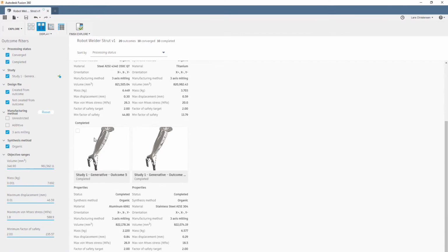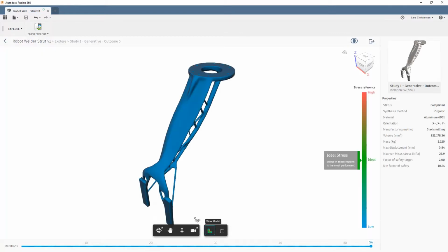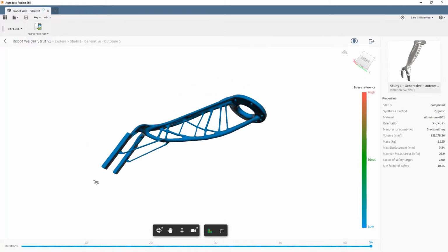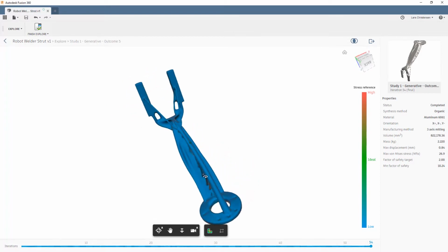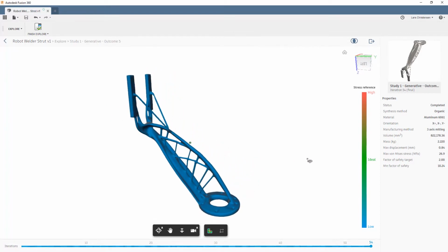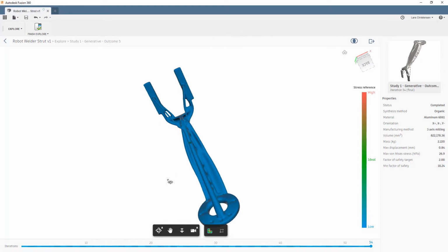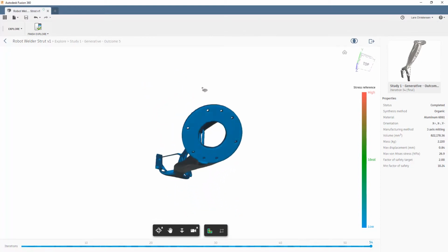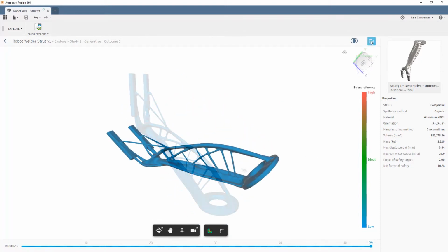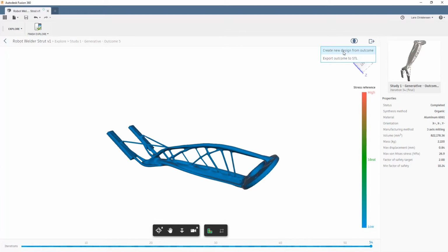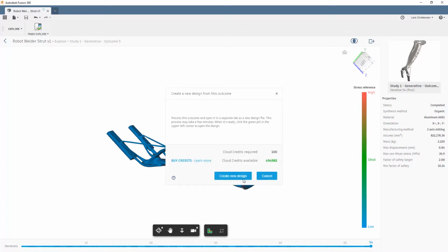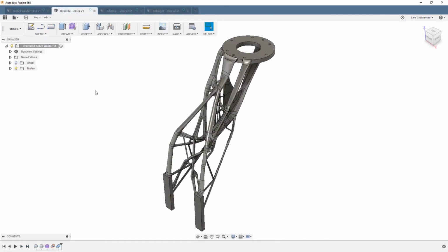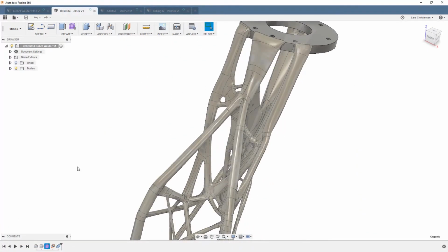Lastly, the subtractive version. Generative Design created this based on the instruction of 3 setups on a standard 3-axis mill, machining from the top and 2 additional setups with the part on the side. In this case, the design team wants to validate each manufacturing process within their Inventor design workspace so they can present the results to management.